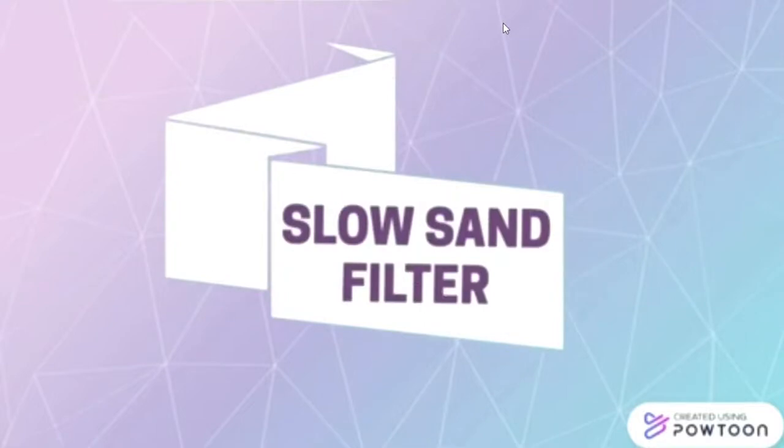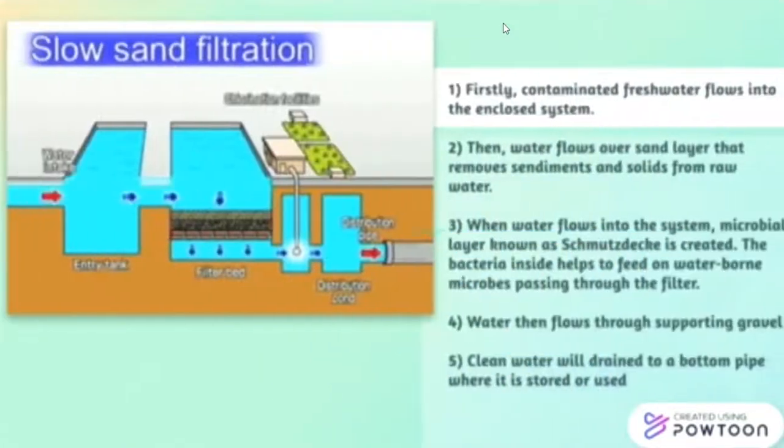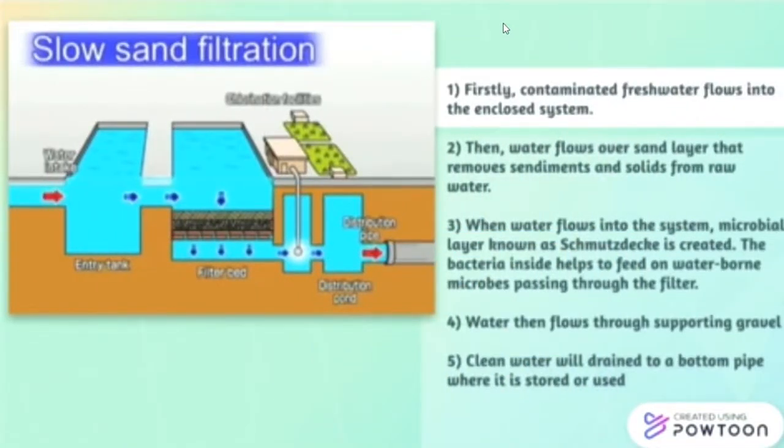Slow sand filter. Do you ever wonder how it works? Firstly, contaminated fresh water flows into the enclosed system. Then, water flows over a sand layer that removes sediments and solids from raw water. When water flows into the system, a microbial layer, known as the schmutzdecke, is created. The bacteria inside help to feed on waterborne microbes passing through the filter. A constant rate of water is needed to maintain the layer. Water then flows through supporting gravel, which supports the upper layer of the system. After the water passes through the gravel, clean water will flow to a pipe where it is stored or used.